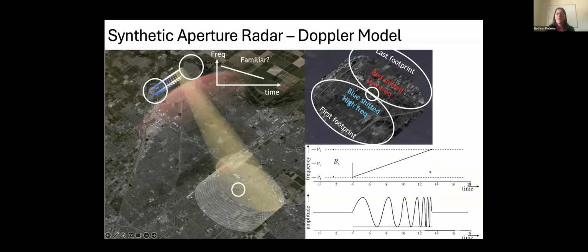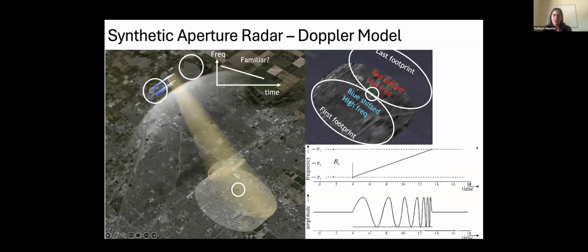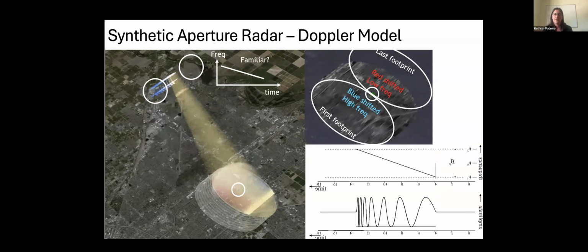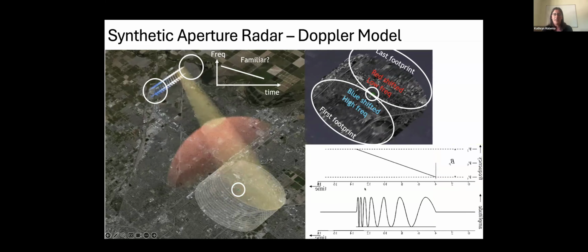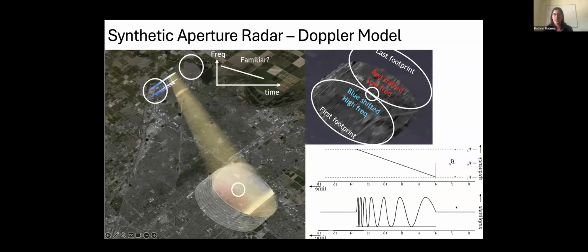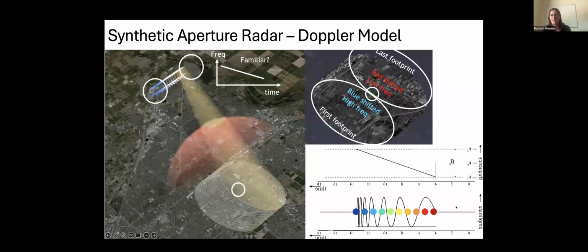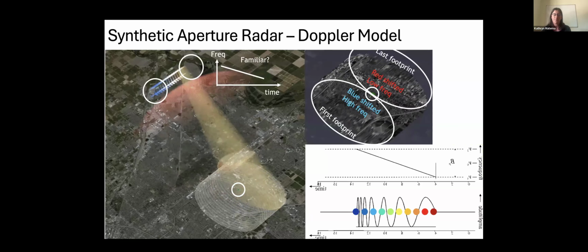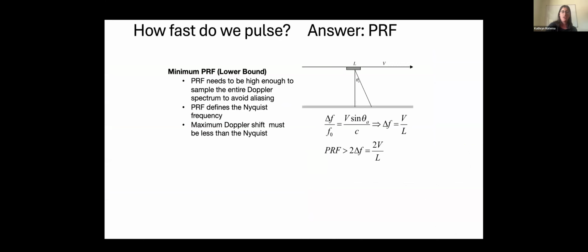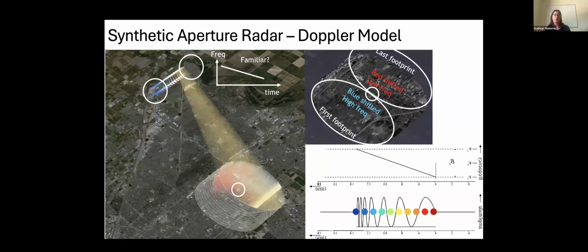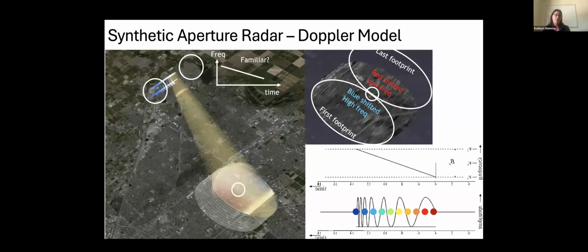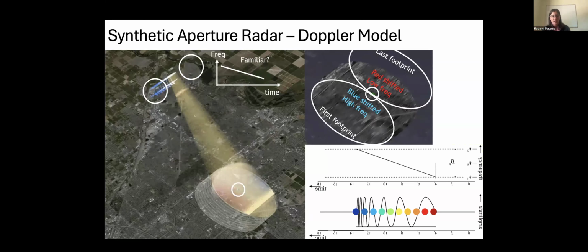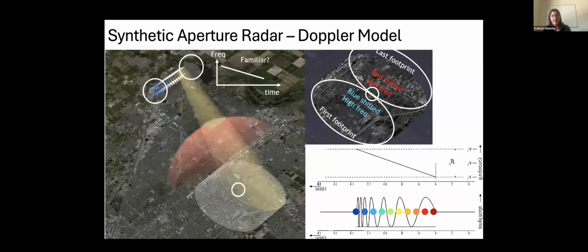Because this is actually the exact same thing that the range resolution is using, the exact same trick, except we flip it because we have the high frequencies first and the low frequencies at the end. And so this is the exact same idea used in azimuth that the chirp is using in the range. And when you put all of this together, you end up with the ability to distinguish pixels on the ground in both azimuth and range at a much higher ground resolution than you would be able to achieve without using this synthetic aperture.